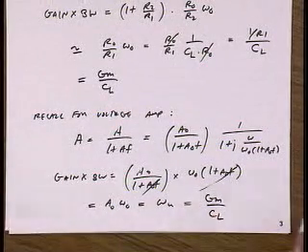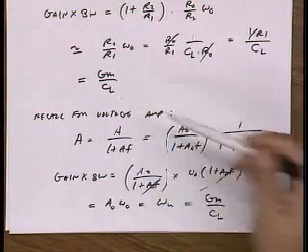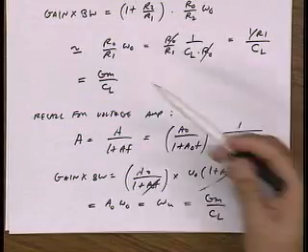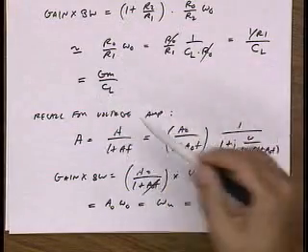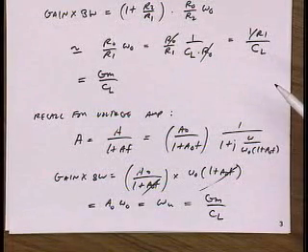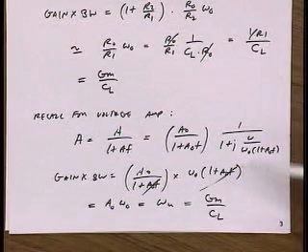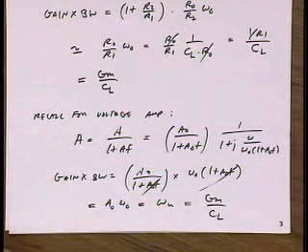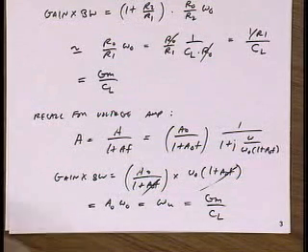Okay, so now we see that at least the answers are in very similar forms. The gain bandwidth product depends on this capacitance, which could be the same in both processes, and also some GM term. So how would you compare these two GM terms? Which one do you think you could make a lot bigger?